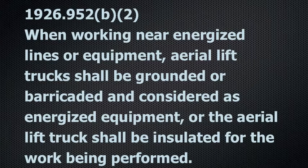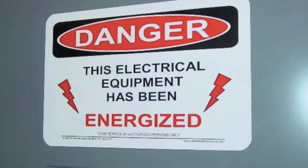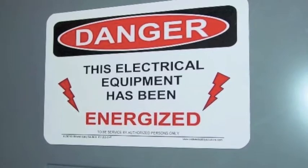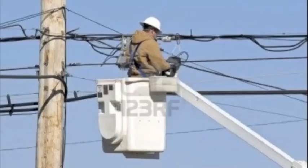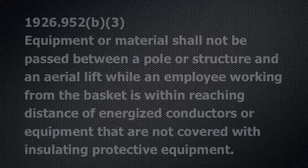Section B2 states, when working near energized lines or equipment, aerial lift trucks shall be grounded or barricaded and considered as energized equipment, or the aerial lift trucks shall be insulated for the work being performed. Here's an example of one of the types of warning signs that would be placed at the bottom of a piece of equipment, such as this bucket truck, that would be considered to be electrically charged.